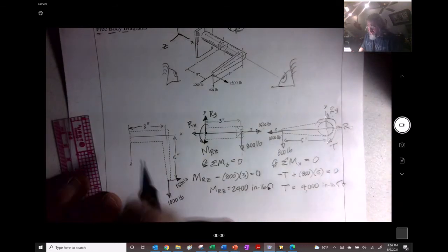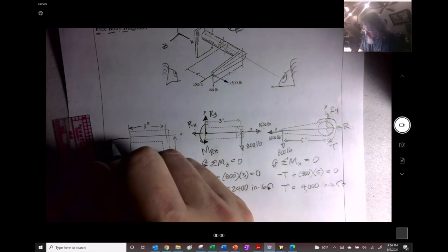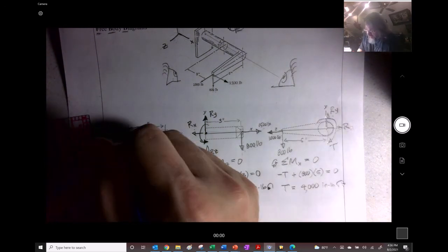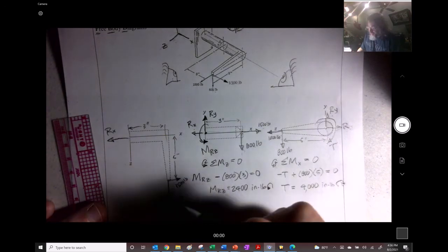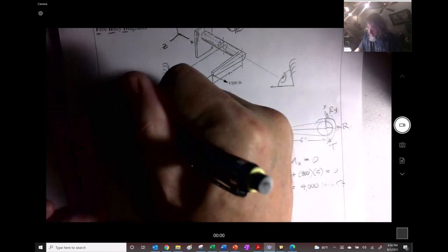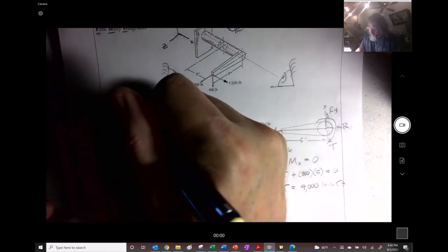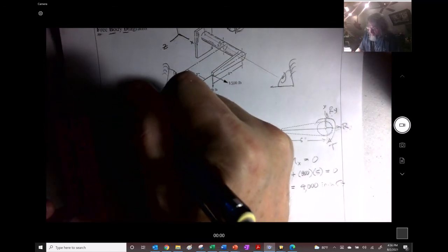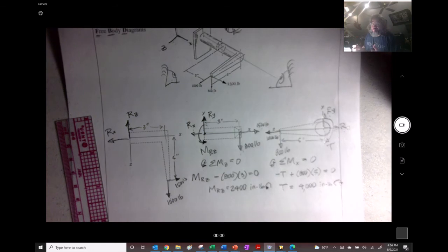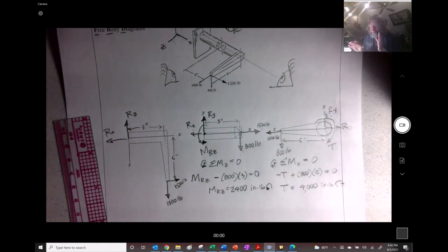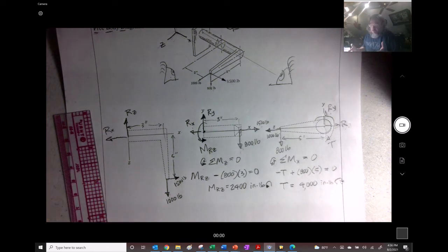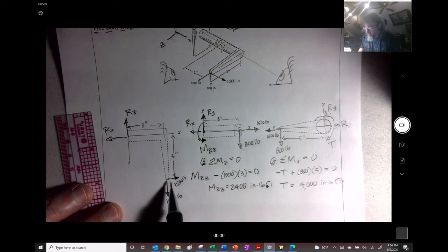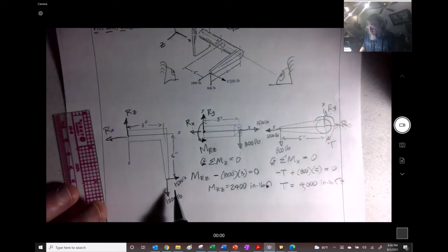All right, so the reaction forces being placed on here: this is going to be Rx, which we would have found from over here previously. And then we also have Rz, which we know has to go in the opposite direction from here. There could be multiple forces on this piece, so we might actually need to write out the sum of the forces to find what the ultimate reaction is going to be. But right here, because it's simple, we just know.